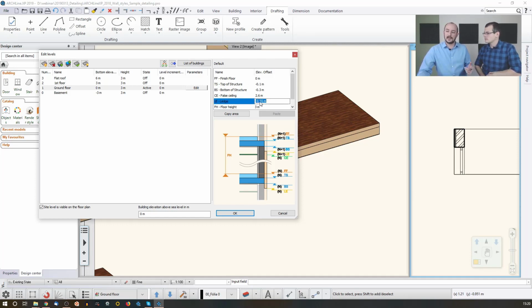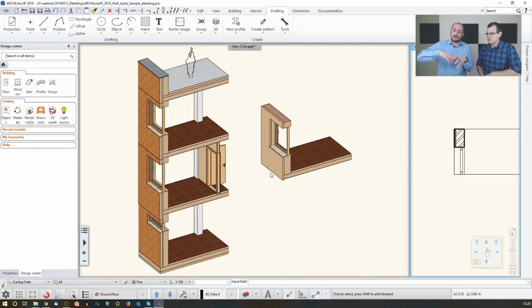And when I modify it, let's say it was not correct, I forgot to set it up, so I need to change that. Sorry, it should be 35. That's what I wanted to say. So it's 20 centimeters smaller. I just say OK. Then the software updates that, and if I already created the whole building with the same setting, the whole building is updated now on this level. So this is not something that you have to update manually for every single wall.